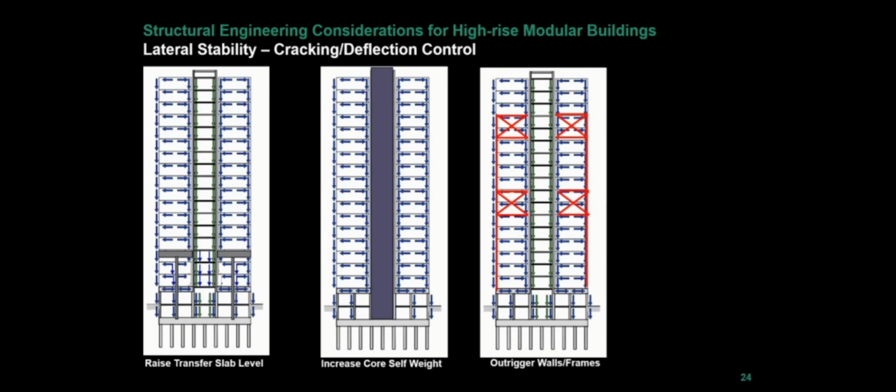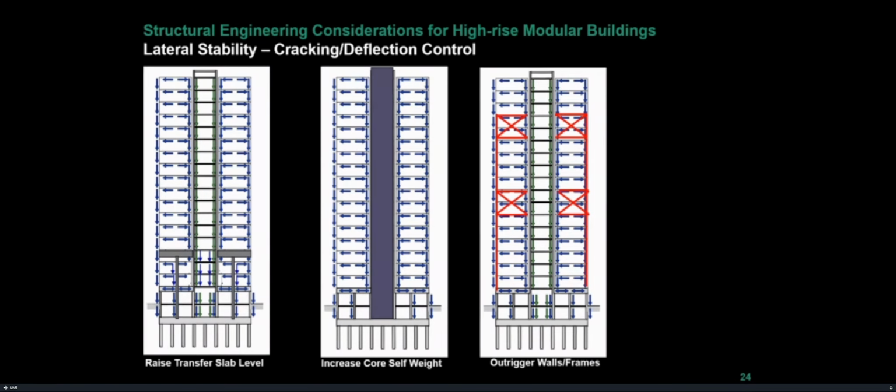And it also gives us the opportunity to put in more shear walls, to really stiffen the base of the building to compensate for the increased deflections above transfer level. You could increase the self-weight of the core, thicker walls, thicker slabs. Can be an easy fix, but sustainability wise, the weight of concrete and cost of materials may not be ideal in all situations.